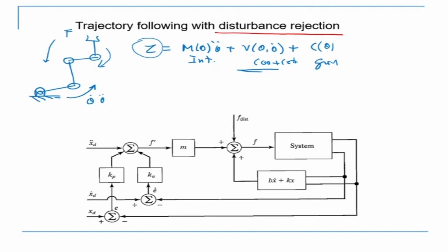What does it mean? It basically means that if I'm trying to move the link in this direction, you can imagine it is going counterclockwise, a counterclockwise rotation, what is the inertia doing? It is trying to oppose the motion, and that is a disturbance. So what is the dynamics of the system doing? It is causing a disturbance on the controller.